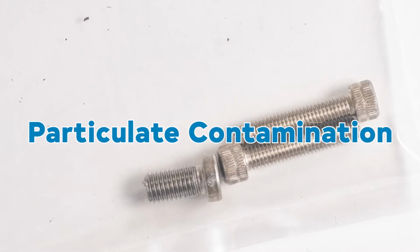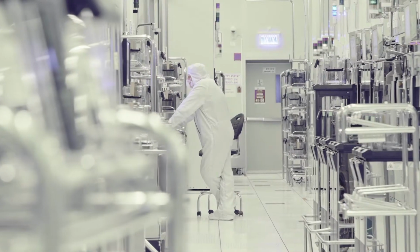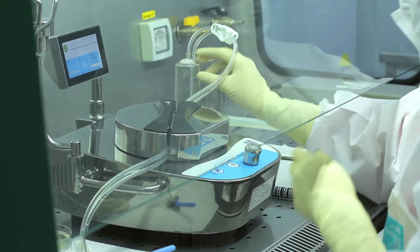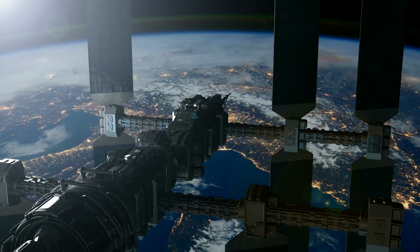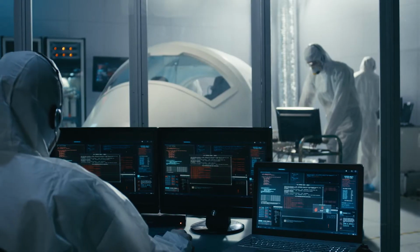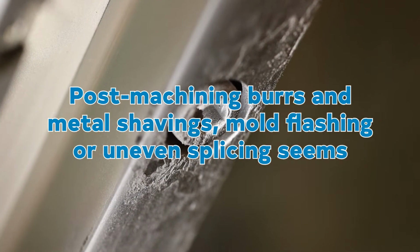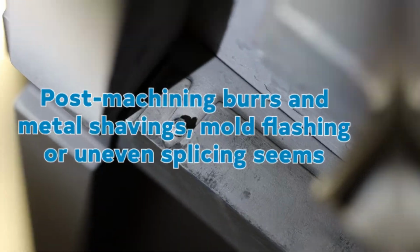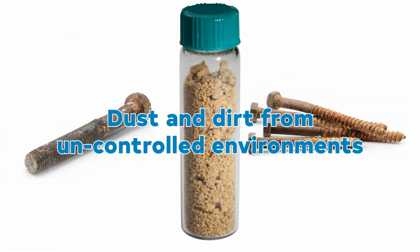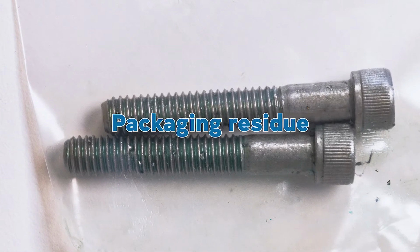2. Particulate contamination. Most semiconductor and other vacuum processing applications, as well as a variety of other clean critical applications, require parts that are free from surface particulate. The origins of surface particulate are numerous, including post-machining burrs and metal shavings, mold flashing or uneven splicing seams, dust and dirt from uncontrolled environments, packaging residue.